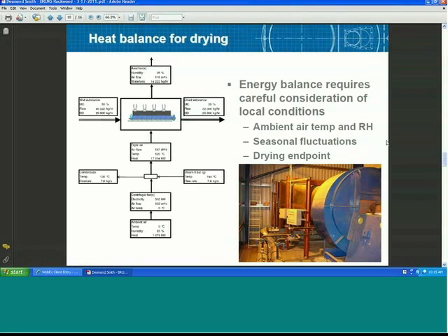In a diagrammatic form, the heat energy balance that we use when we talk about these drying processes looks like this on the right. There are essentially three things going on. Going from left to right, we have wet substance coming in, which is composed of fundamentally two components, the bone dry material and the total flow, the difference being water. The bone dry material into and out of the dryer is the same, and the difference is the moisture that we're driving off.